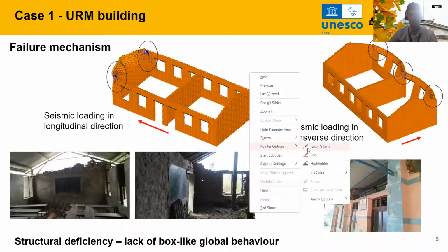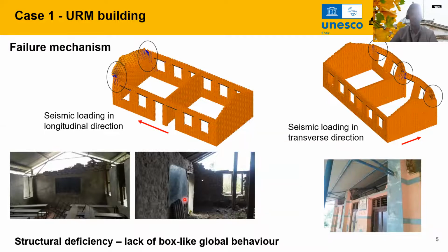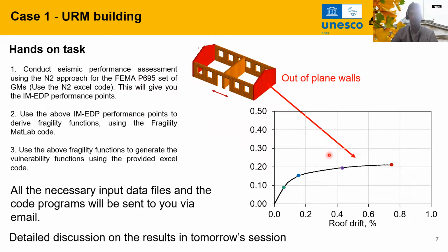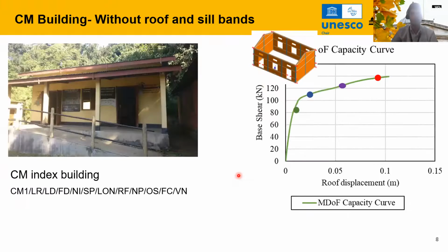building with respect to the in-plane and out-of-plane systems. Accordingly, we have derived the pushover curves and the damage registers for each of the in-plane systems and the out-of-plane walls separately. For this task, we are requesting you to take this out-of-plane wall, this pushover curve, and these different damage registers, and perform the analysis only for this out-of-plane wall. Not for the building, not for the in-plane system, only for this, and we will provide data only for this. So you are only required to analyze the out-of-plane wall.